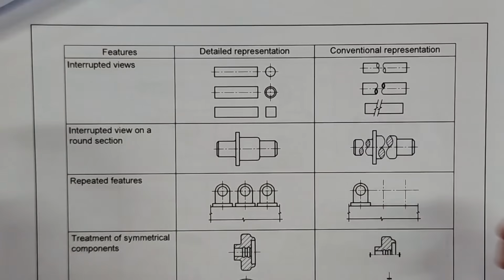Then here are the gears that I referred to earlier. So bevel gear with its conventional representation, never going to draw all of those gear teeth in there. An assembly, bevel gear assembly. I'm doubting that this will be asked in a way of just, go and draw a bevel gear, but they might want you to identify it.